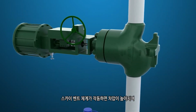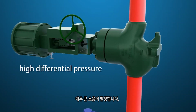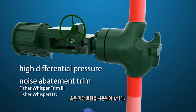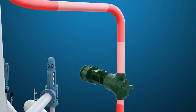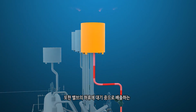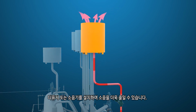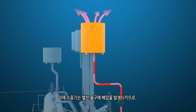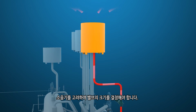When the sky vent system operates, it has a high differential pressure that creates very loud noise. A noise abatement trim, such as Whisper 3 or Whisper Flow, should be used in the control valve. There will also be a diffuser or silencer downstream of the valve that discharges to atmosphere to further reduce the noise. The valve will need to be sized with consideration for the silencer, as the silencer will create back pressure for the valve outlet.